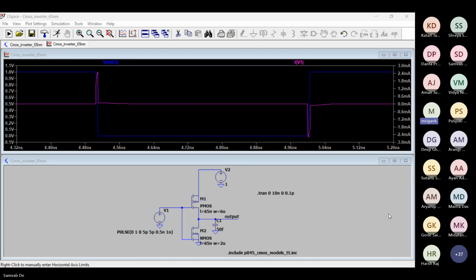So the moment you have increased the gate sizes, the MOSFET sizes, that means you have increased those capacitors. That means the current being provided by V1 will increase because now it has to charge a bigger capacitor. The CGS has increased. As a result, the load capacitor for V1 has increased, and now the power consumption because of V1 will increase.